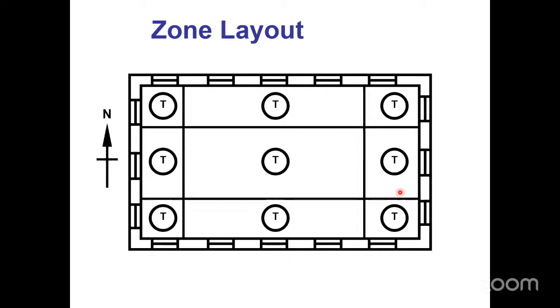But putting the conference room on with an office is a disaster. That conference room might have 15 people in it, and all of a sudden it needs cooling while the office over there needs heating. So if there's a conference room, you always split it off on its own. If there's a classroom, you split it off on its own. Those spaces get used differently. So you need to divide the zones based on the cardinal direction that they're facing and how they're utilized, time of day, and occupancy variability.